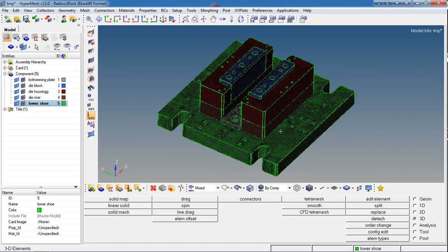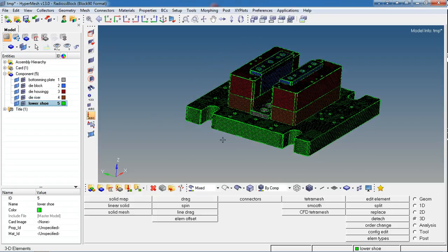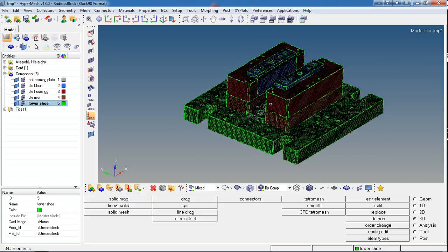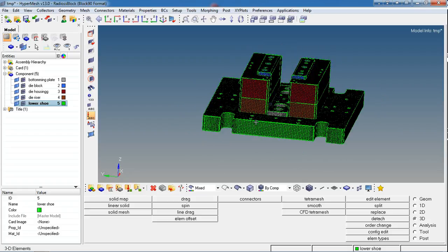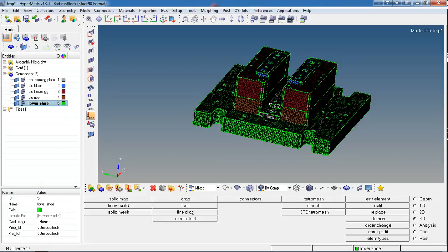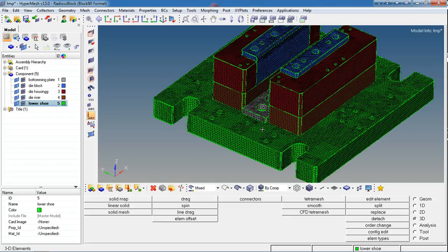You must check the element quality parameters such as the Jacobian and warpage. Likewise, you correct everything. There should not be any failing element against the criteria of the mesh as per the industry standards. After that you will have better accuracy in the results. After performing this check and then refining of the mesh, I'm skipping that actually because that's not an easy task. That's a time consuming and lengthy process. Therefore I'll be skipping that.